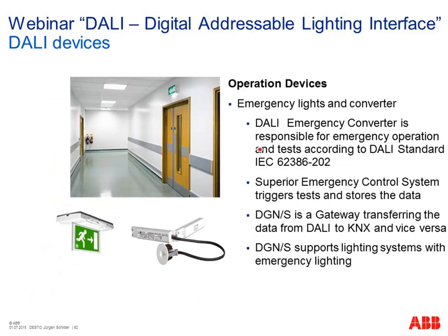Good, and DALI supports also self-contained emergency converters. It is also specified here in this IEC DALI standard. So it is possible to connect these devices like the route escape signs or here the emergency light with the LED. And via our superior system like KNX, we can also monitor these emergency lights and converters. These devices must do maybe some function tests or battery tests several times per year, and the test result can be recorded or sent to KNX and then recorded in our KNX world.